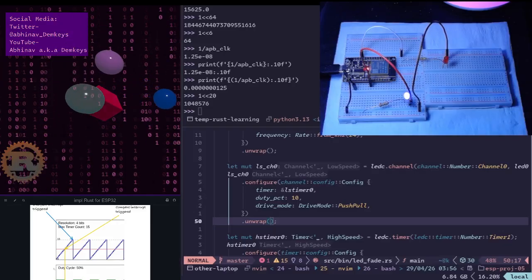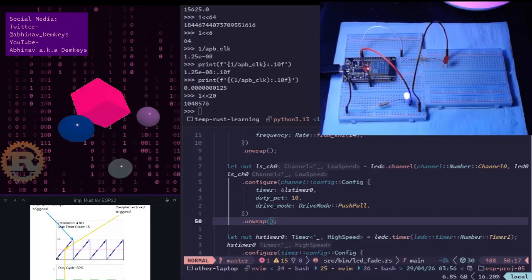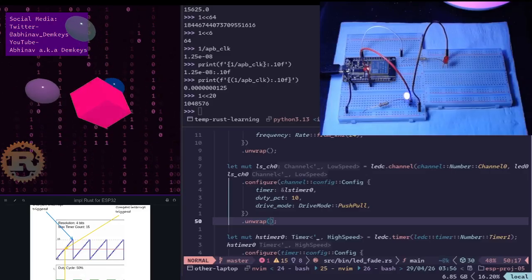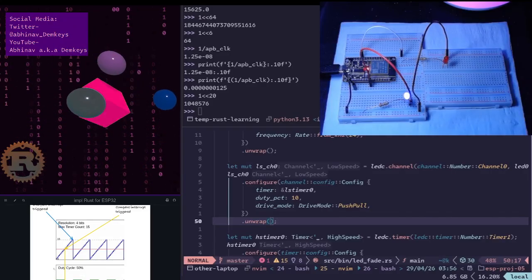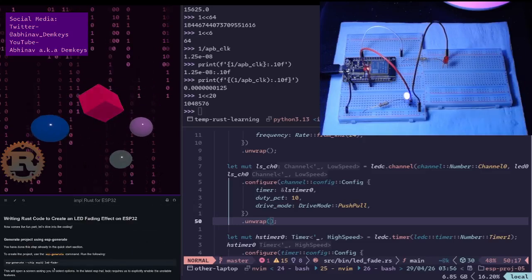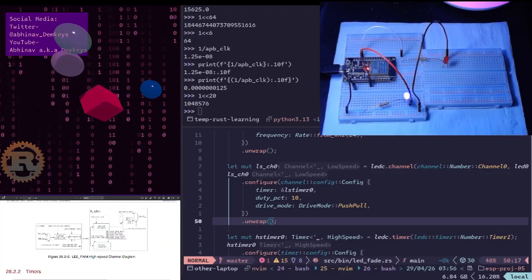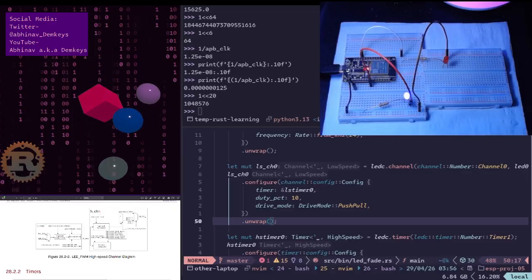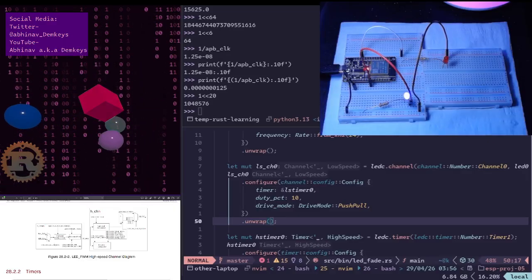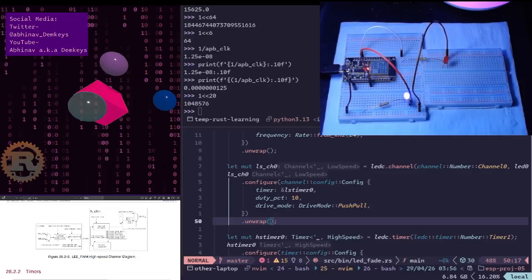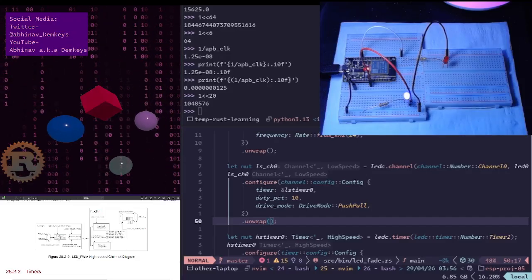Okay, now the interesting thing here is that we have our resolution bits. We have our counter register, which is a 20-bit register. Wait, let me come back here. Does it also mention in this diagram? Yeah, it mentions here as well. Counter 20-bit and fractional divider 18-bit. So our counter is 20-bit. Our fractional divider is 18-bit.